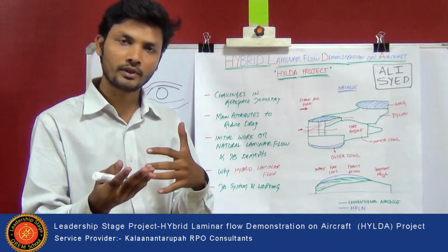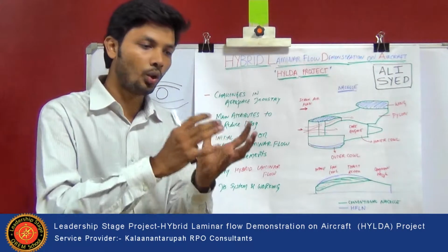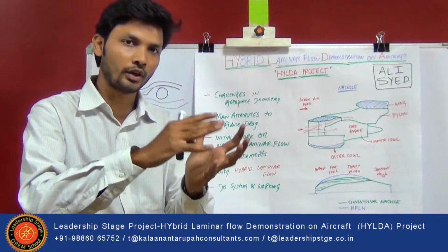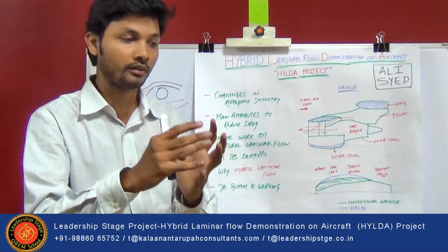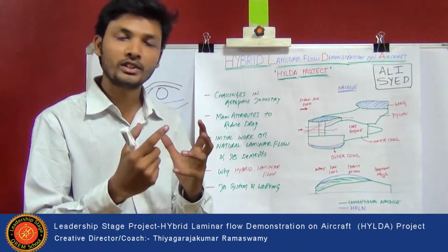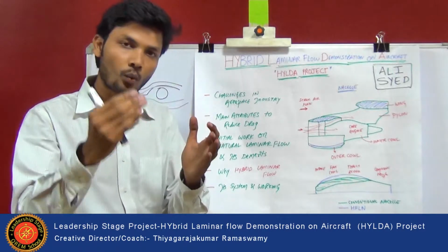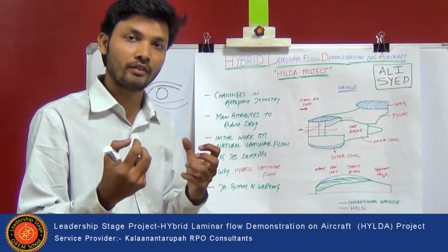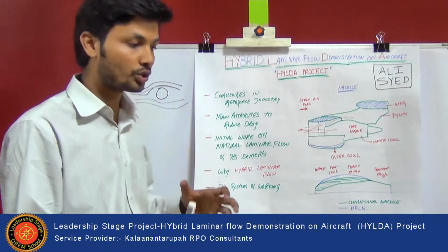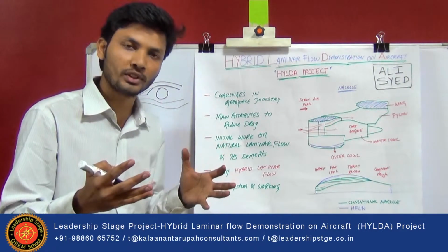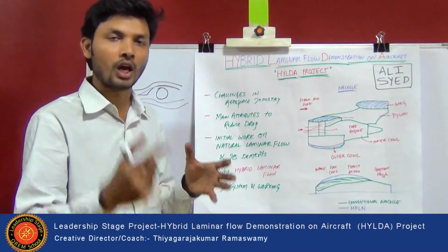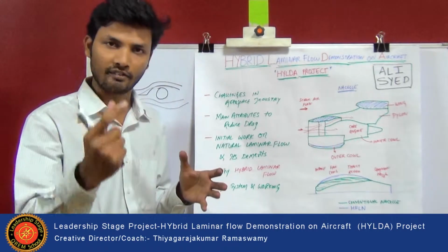With the commercial planes which are in use at the moment, the whole aerodynamic drag coming from the design of the aeroplanes takes 4% of the engine thrust, which is very huge. Even if you decrease the aerodynamic drag by 1%, the fuel consumption saved because of that will be very huge. So now the most important attribute of aerospace design is how to reduce the aerodynamic drag or friction drag.